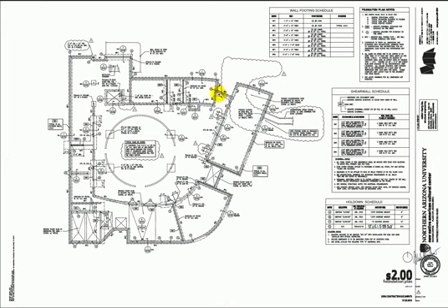So now I have a good feel. There are little strip footings around the perimeter. Remember from the general notes they had to be 2'6" below the exterior grade or the finished slab. In this case the exterior grade was lower. So that tells the contractor how deep to go. You'll note on the drawings it didn't give any elevations, which puts a lot on the contractor to figure out.